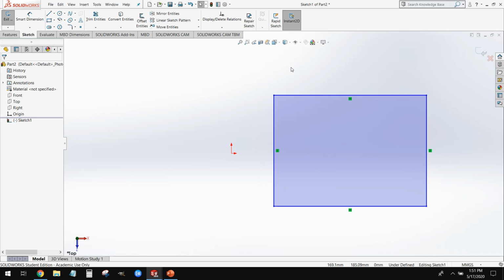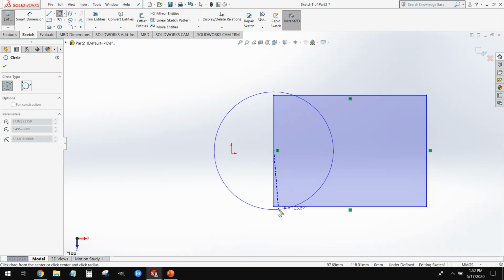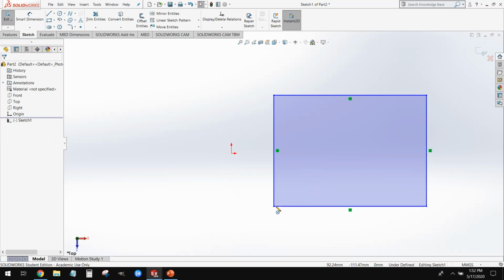What I want in this is to be able to use my origin later on to position that large circle. Now, I want that large circle to overlap right like this, and we're going to draw this later on. So what I'm going to do is position my origin so that it's in the midpoint of this line. The way we do that is by adding a relation.